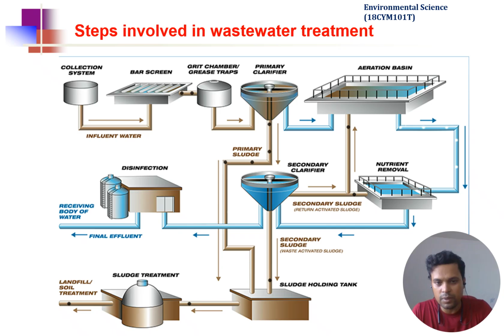And then after we remove all these nutrients, which are salts, you can bring it to another sedimentation tank, and from there we can go to the disinfection chamber, where you can use different methods like chlorine treatment, UV light treatment, or ozone treatment. Okay, and finally it can be discharged, or it can be taken to another plant where it would be purified further for normal daily use or for drinking water.